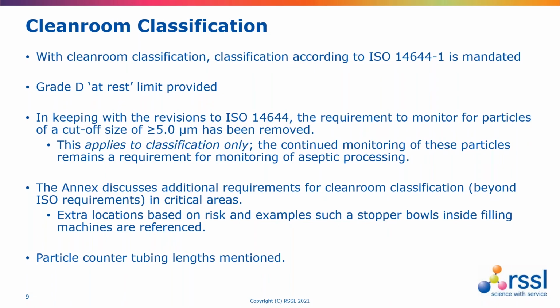Now there is a change that the 5 micron count is no longer a requirement for classification, and that's in tune with the ISO 14644 standard, so it is optional. However, there is no change for continuous monitoring, particularly for sterile product manufacturing. So the 0.5 and 5 micron particle counts will remain very much in place for standard monitoring.